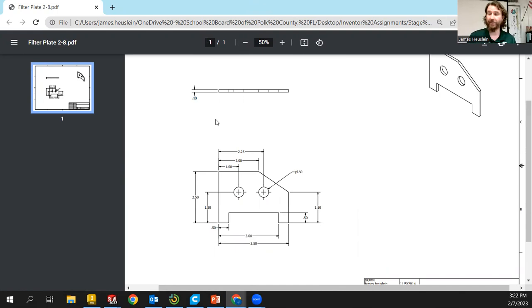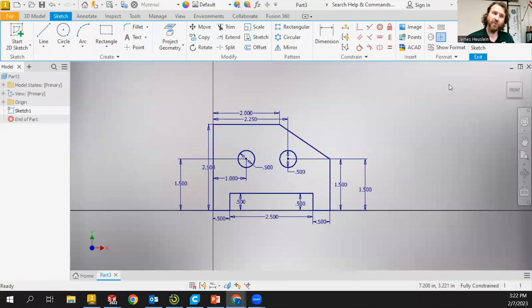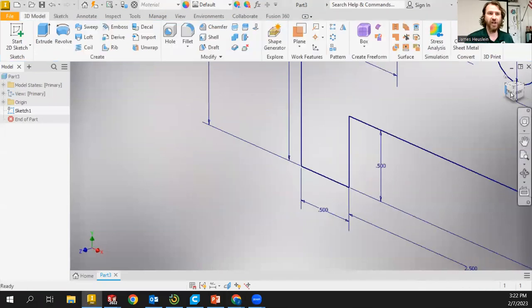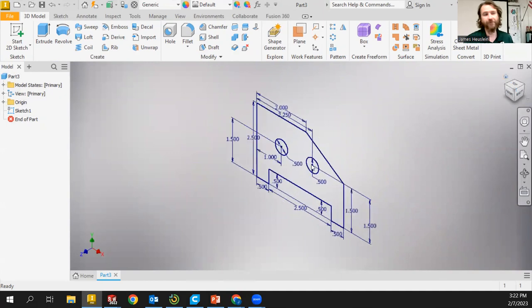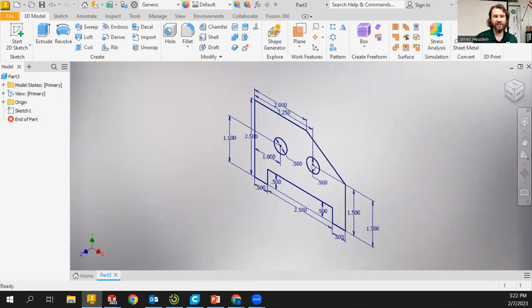The next step, and in this case, our final step for this particular part file to make it 3D, is to extrude it. So that's what we do next. Right? So this is done. We can finish the sketch. We're going to hit the green check box. It does this weird zoom out thing. You can hit the home key there that's just above the view cube, or you could hit the corner of the cube itself. Either way, you get a nice isometric view of this sketch.